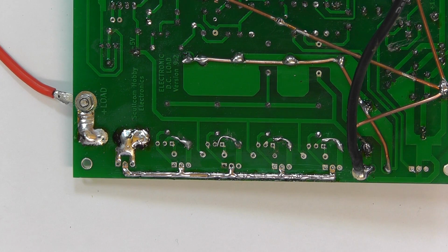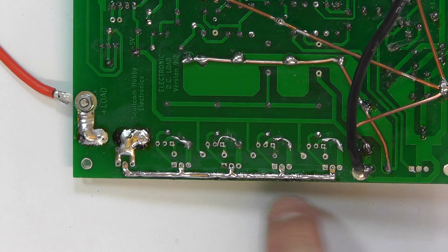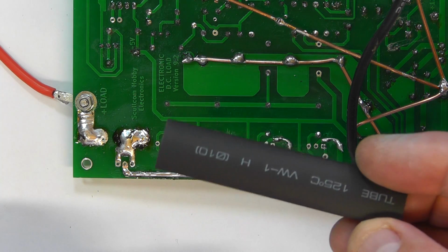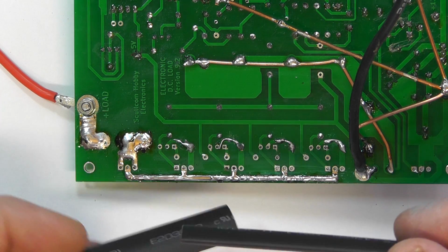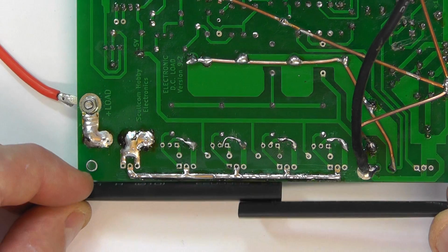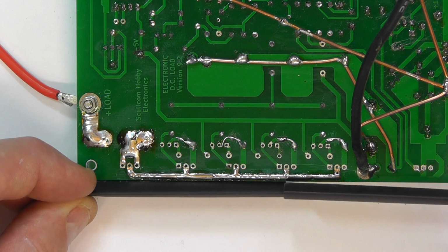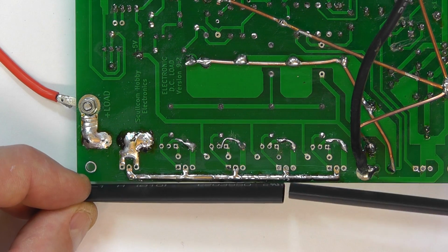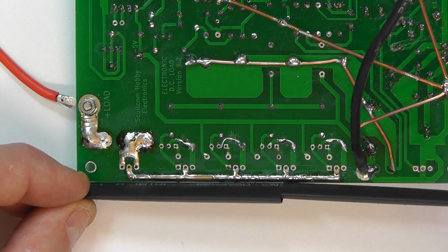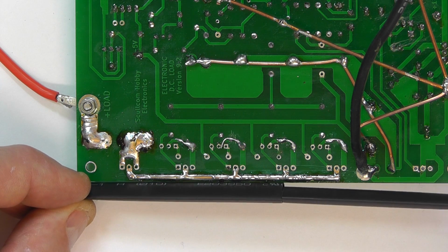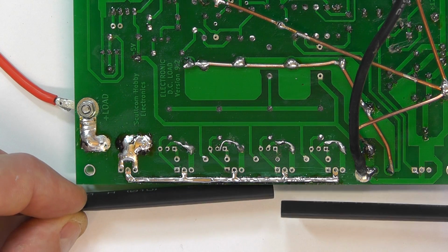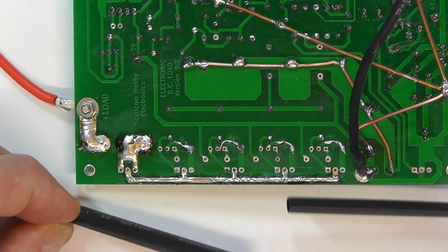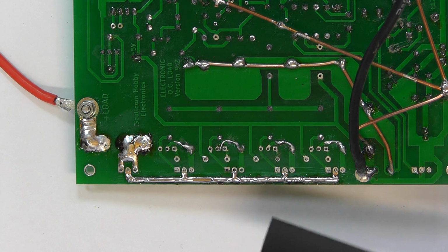Now one option you could use just to make sure that the board itself is not touching the heatsink is to use some heat shrink sleeving, so it's heat resistant, and then we can maybe position that on the edge of the board, butt it up between that and the heatsink just to give it some insulation, so there's nothing touching the heatsink itself. So you can either do that or simply just make sure that it's standing off from the heatsink, as I say, either 1 or 2 millimeters.